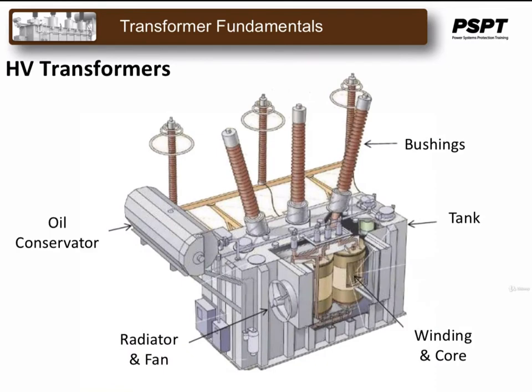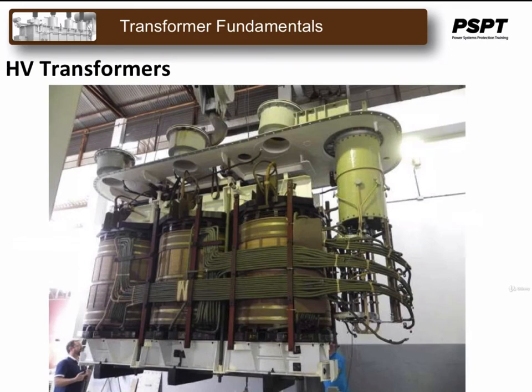Some protection functions, such as overexcitation protection and temperature-based protection, may aid this goal by identifying operating conditions that may cause transformer failure. The comprehensive transformer protection provided by multiple function protection relays is appropriate for critical transformers in all applications. The type of protection for the transformer varies depending on the application and importance of the transformers.